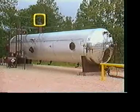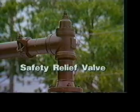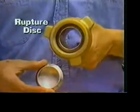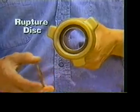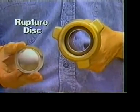The safety relief valve, or pop valve, is designed to open at a preset pressure level to relieve excessive pressure within the vessel. A rupture disc is a fail-safe pressure relief device. The metal disc is designed to burst at a predetermined pressure level. This pressure is usually set at or below the maximum safe working pressure of the treater.